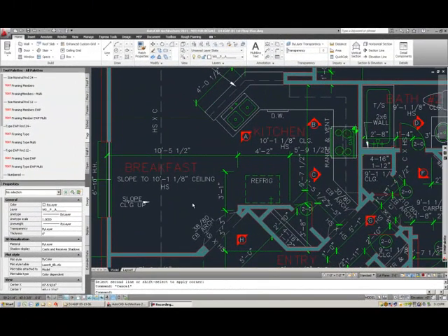One of the bigger differences between 2D drafting and BIM modeling, building information modeling, is layers. Typically in 2D drafting, a drafter is always consumed in calculating what kind of layer to put on their drawing. Layers are typically a named layer with a color and a line type, and the color is the most important part because the color translates to how the line is actually plotted. So the drafter always needs to make sure that the layer is on the correct color so it comes out properly in the printing process.